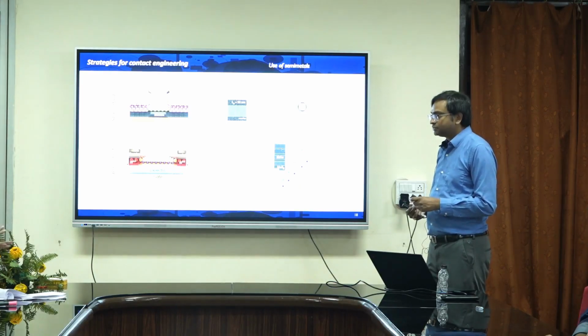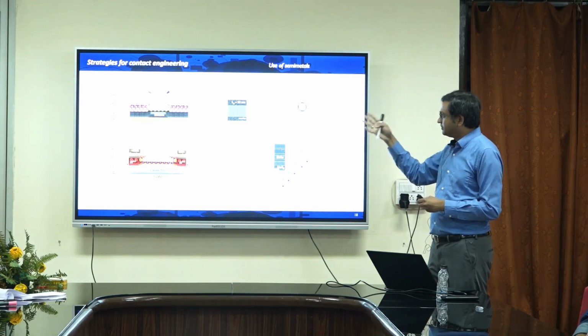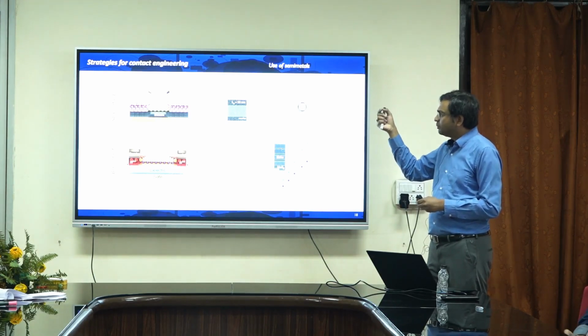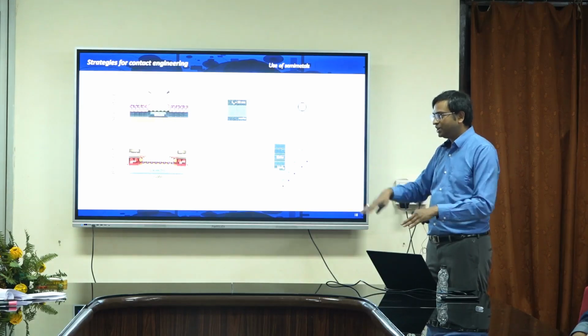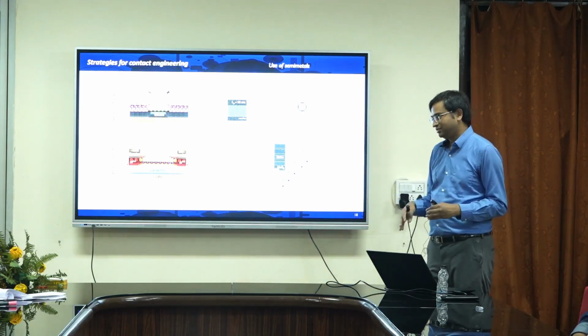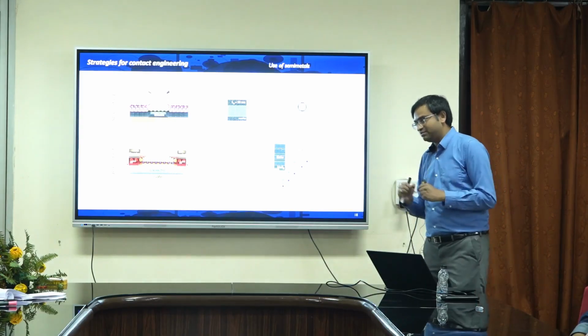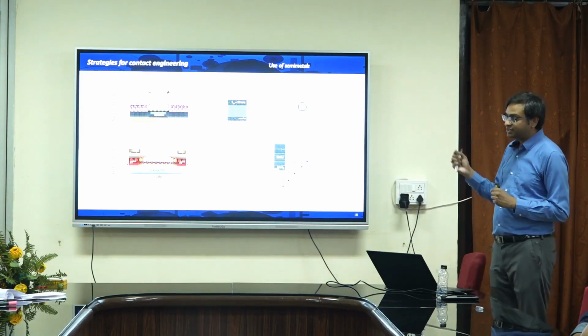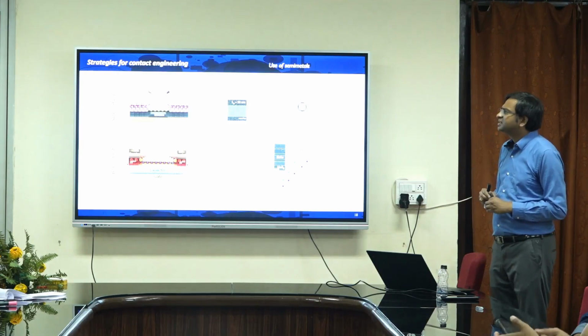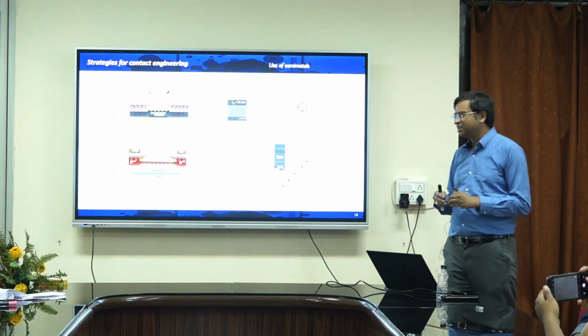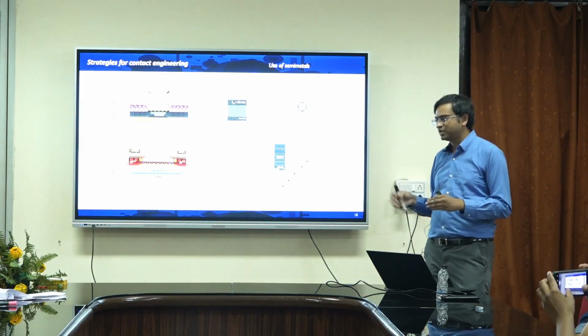Yes, it's a capping layer, because of two things: antimony may not be very ductile, and practically you have to land your probes, and you may scratch it. So gold is actually good to have as a capping layer. The thickness doesn't matter actually. It's all based on the lithography. You can use 10 nanometer, 20 nanometer.